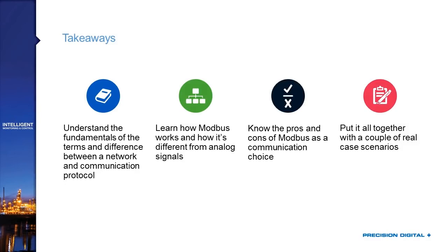We'll want you to understand the pros and the cons of Modbus as a choice of communication protocol, but also versus those analog signals. And hopefully you'll take away something from the real-world example that will show you some of the advantages of using Modbus when it's available to you.